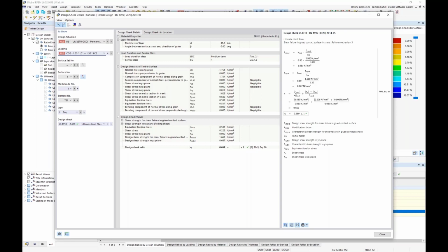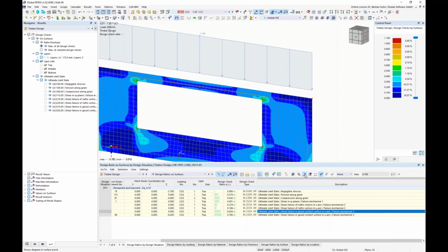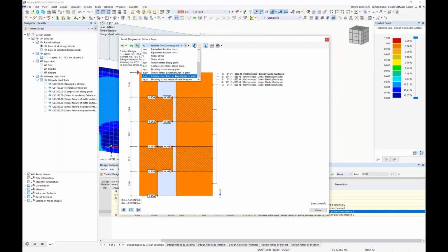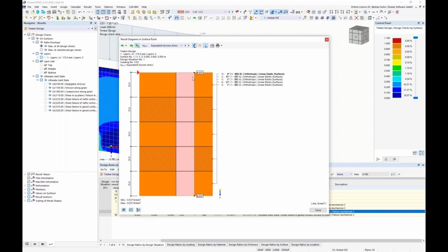So you see here in the details that you have the torsional shear stress of this value, and we are also doing additionally shear stress in X and XZ direction. But you see that the contribution of this is very, very low. So the basic point of it definitely is the stress of the torsion. Okay, tau tor X, that's here. Of course, it's constant over the whole section. That's always the case for this kind of stress. And here you have it in the net section, which is failure mode 2. Okay, good. To me, it worked all nice, or quite well.